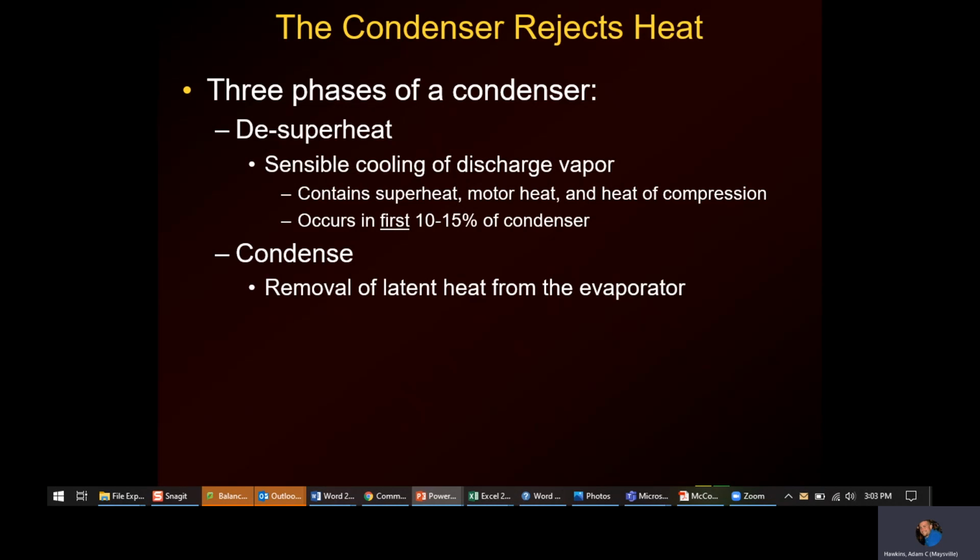You would measure line temp compared to refrigerant temp, and then subtract its saturation point, which is going to tell you the superheat that you're removing. I know that's confusing, so don't worry about all that. You just need to know that it's there.